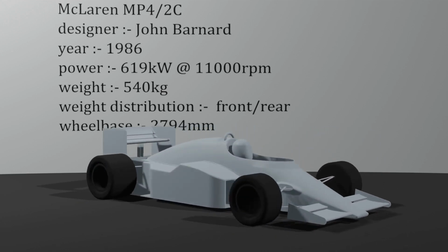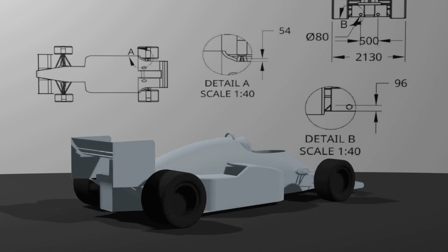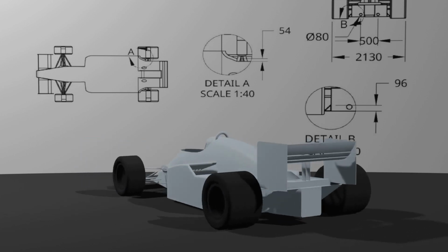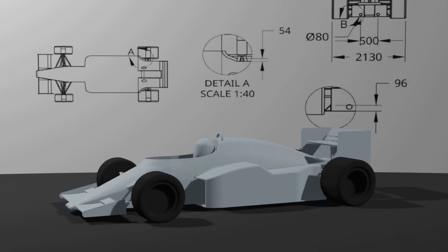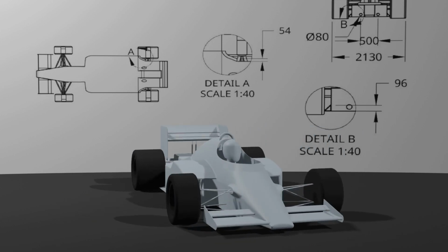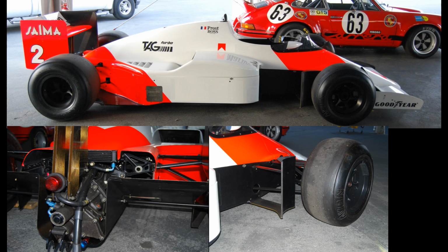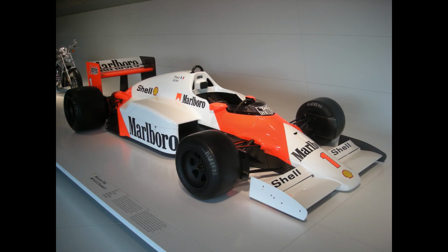Even though it was definitely not the best car in 1986, the improvements made in 1985 were significant in the context of Formula 1 aerodynamics. Ignoring all the mechanical improvements, which there were many, we focus on 3 different features from the 1985 and one from the 1986 car. In 1985, the winglets were outlawed, changes were made to the rear wing end plates, diffuser, and a vertical deflector added inside the front wheel. The change from 1986 was the front windshield.